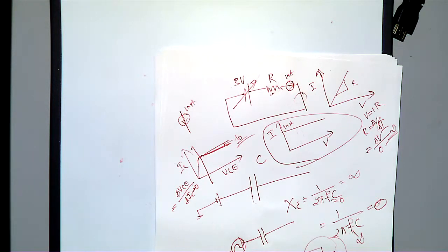So this is for NPN, and then we got the PNP transistor. And then this is for PNP. So NPN and PNP got the same small signal model. So when you draw NPN, so V in, and again you got R pi, then you ground it, and then see, please remember when you put this positive, this negative, the current direction is down. You can put maybe this positive, this negative, then it should be up. But then I have put this positive, this negative to make this down, but you can put maybe this negative, this positive, you can make it up. It's up to you.